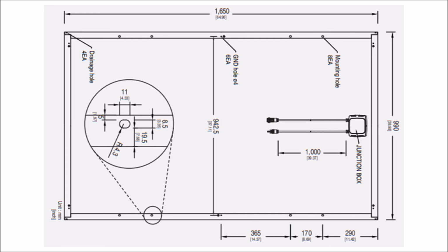The detail on a module spec sheet can assist racking planning. Some manufacturers will hollow out this piece of metal in the module frame to save a little money. The US manufacturer SolarWorld does this with some of their panels. On standard solar, though, the robust module frame allows the racking underneath to run in portrait or landscape orientation. And so the solar panels can be designed in both orientations unless they have a weaker module frame.